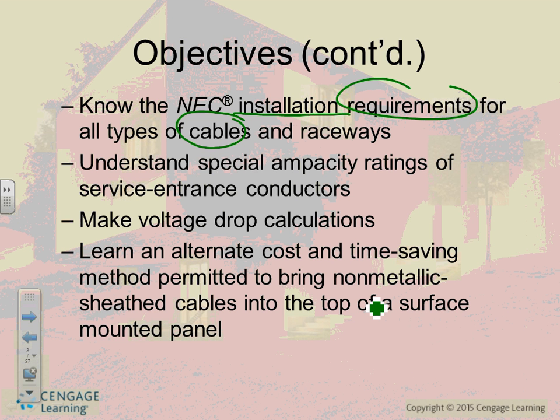So, Brandon, you see they're using a cable tray at the airport. So you go to Chapter 3, look at cable tray, and it will tell you how to size a cable tray. Does that make sense, guys? Because we don't go over cable trays. It looks like a ladder, and you put the cables inside it. But there are rules on how to put the cables. You don't pile them up. You have to separate them by the diameter of one conductor, so one conductor space, then another conductor. And how much current the conductors can carry in a cable tray is different than in a cable. So there are a few rules.